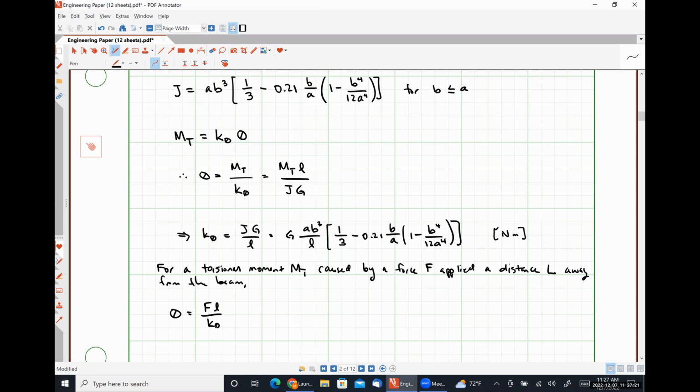which I don't think we have time to do. So we might revisit this, or I might work out an example and then just upload that so that you guys can look at it to see what the displacement of the structure that we are applying the torque to would look like. But the angular displacement is good enough. If we know that and we know how far away we applied our force, it's just that angle times that capital L gives us the displacement of the thing we applied the force to. So anywho, all right, so this is all of our springs. So we are roughly 2/3 of the way done with our review of things.